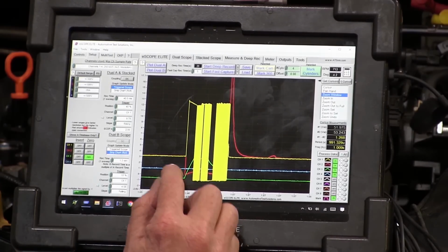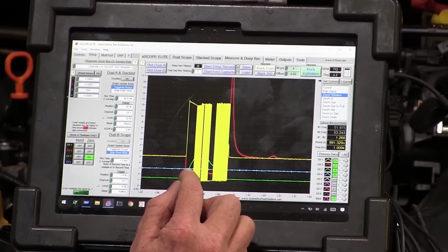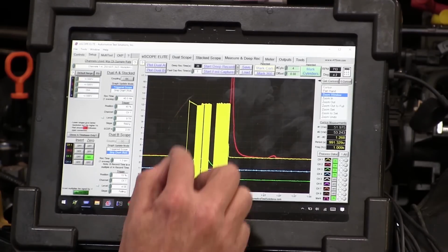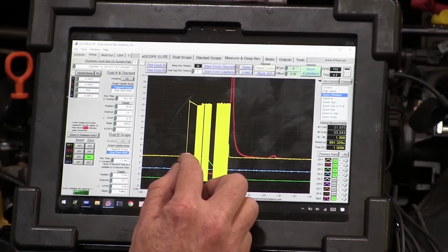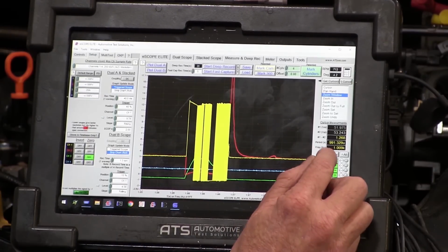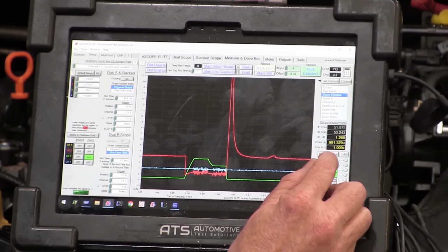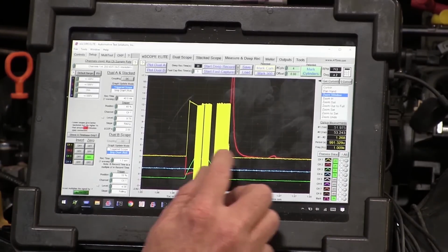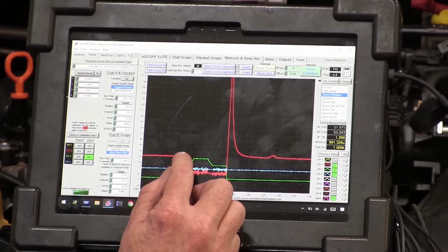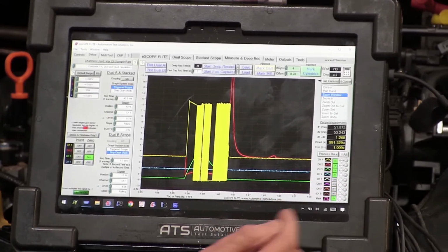Okay, notice how the voltage went high and I got a ground. This is very common on how Honda controls this. They get full voltage and full ground and I build current really quick. Then I start to pulse the voltage, and that's a current limiter. Do you see how the current came up real fast, and then I limited it? Right when I start to pulse it, this green is my current, and you can see how it limits right when I start to pulse.